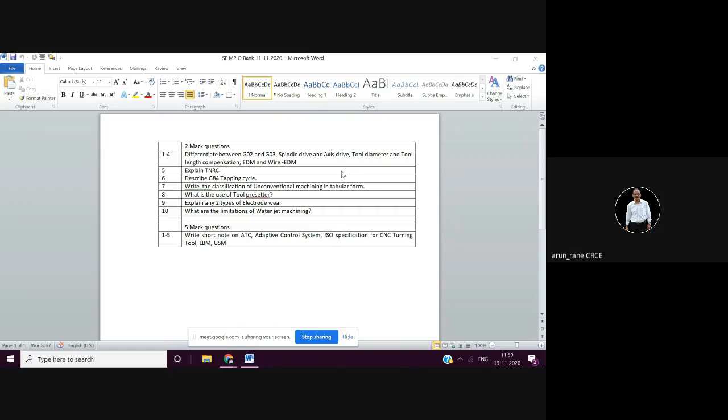In the case of a drill, reamer, tap or end mill, the diameters are fixed. There you don't have to do any setting of diameters. But in the case of a boring bar, you need to set the diameter as per the bore because every boring bar will have a certain range. Every boring bar has a range of minimum 5 mm to maximum 10 mm.